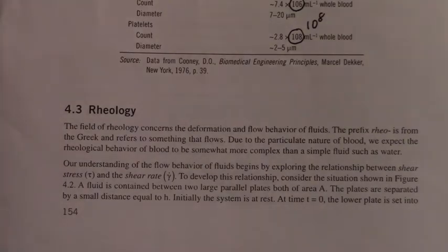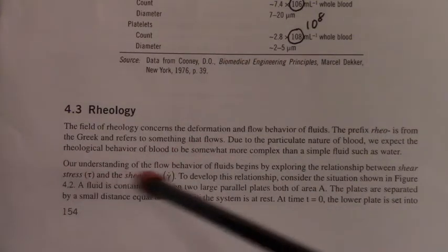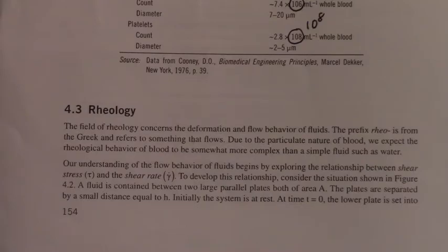If you were taking movies of your deformation of a deck of cards, and you did this at different speeds of movement of your hand, you would start to see that there's a relationship between the applied shear stress, how much force you apply to the deck of cards, and the rate at which the deck of cards is deformed. The same thing is actually happening within fluids, and we can come up with a thought experiment to investigate this. What we're interested in finding is what that relationship is for a fluid between the shear stress and the shear rate.